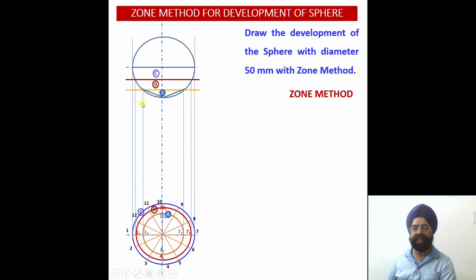Now as we had discussed, you see this is my first slice. Whatever first slice is obtained, we are going to assume, using the approximation method, that this slice will behave like a cone. So the development will behave like a cone. If we say this is a cone, this is my slant edge, please check.